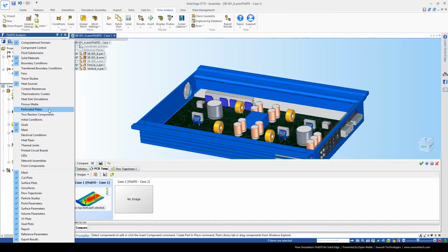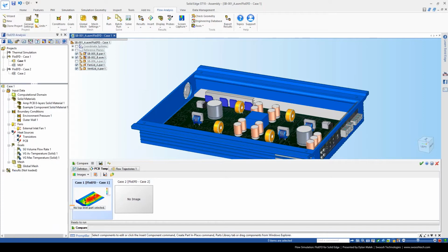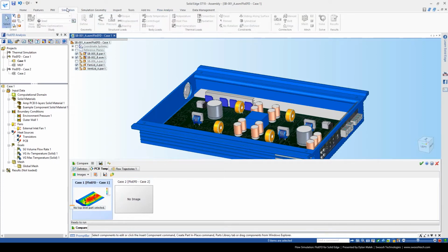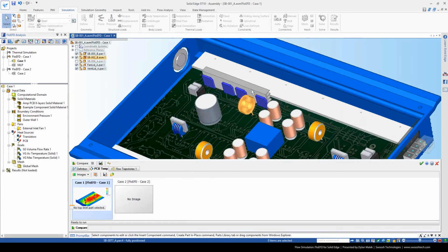There's an LED scenario, and there's thermal. Again, in Solid Edge, we do have some thermal tools built inside of our simulation. These are, for example, if I want to see if this heat sink gets a certain amount of heat from these, and is that going to transfer that heat to another part? So we do have radiation, convection, heat generation, and flux built into our advanced simulation that's part of our assembly. But as for the airflow of showing the volumetric flow of air through this product, that's where it stops. That's where we flip over to flow analysis, and that's where these guys do both.